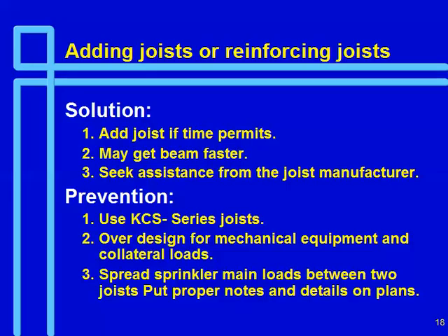But we don't do that, do we? We try not to. We do our best. Remember, just another thing that comes up are sprinkler mains, you know, the 8-inch main. Make sure it gets hung from more than one joist. Otherwise, it'll overstress it for sure, unless you've designed it that way.